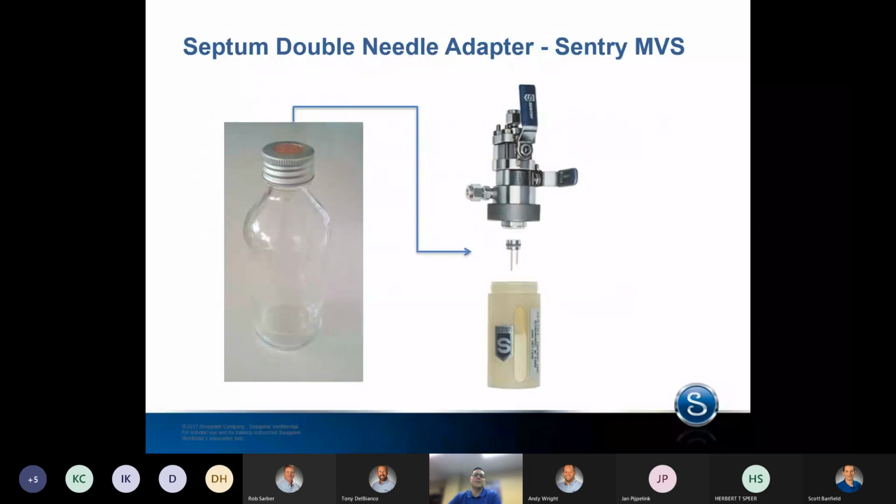And again, this is the key to that panel. This is the MBS Sampler. It utilizes a deadman handle on the valve, which we'll show you in the next animation. It's safe. It uses that double needle septum style bottle collection, which we hit on, which has that environmental seal. It has a shroud system, so it helps guide the bottle up into the double needle system, and has a rest bar, so again it takes it out of the operator's hand while collecting. So there are some nice safety features to that as well.